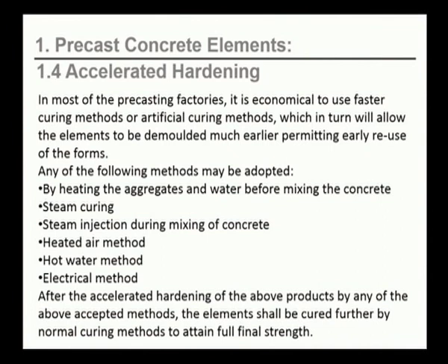After the accelerated hardening of the above products by any of these accepted methods, the element shall be cured further by normal curing methods to attain full final strength. Curing. For any concrete component, curing is an important part. The curing of the prefabricated elements can be effected by the normal methods of curing, of sprinkling water and keeping the element moist. This can also be done in case of smaller elements by immersing them in a specially made